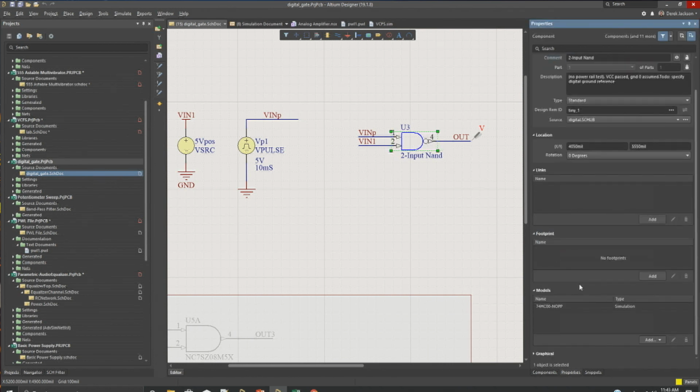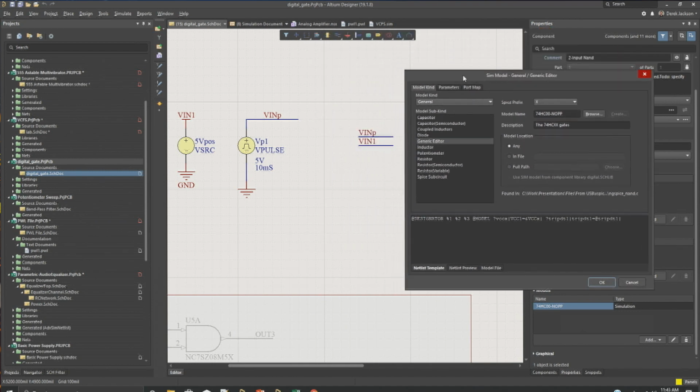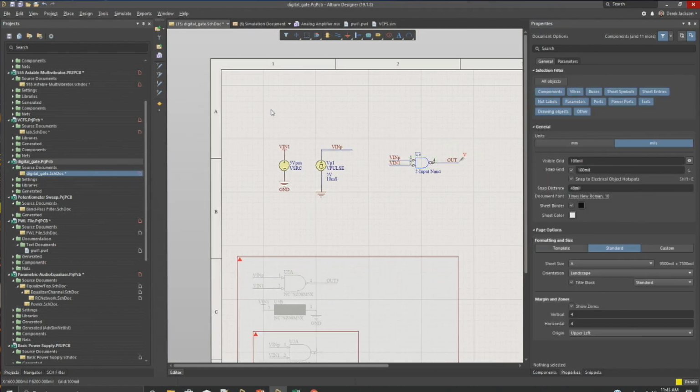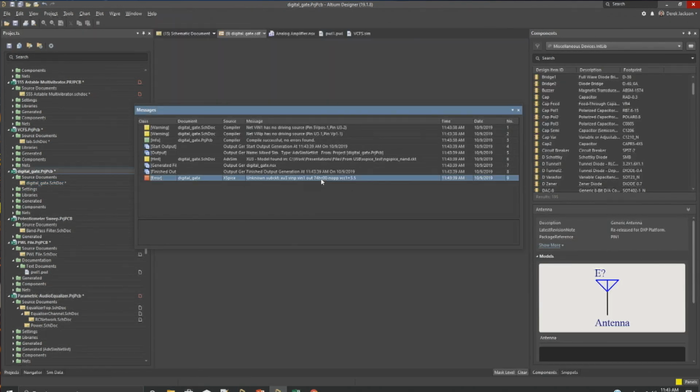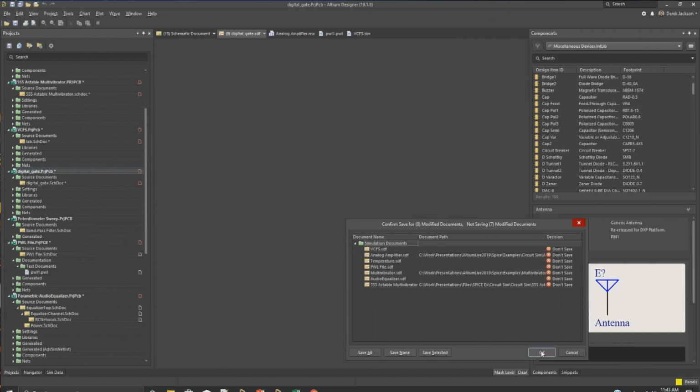So this is just a digital AND gate. When you download the older legacy libraries, there's a lot of digital SimCode models. All of our digital components are done in SimCode, so all of your ANDs and ORs and all of the digital gates. I'm not sure if this one is just an XSpice one. I haven't even tried it in 8.0.19. Yeah, see, it's saying unknown here, as I had been doing in 8.0.